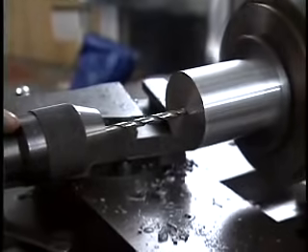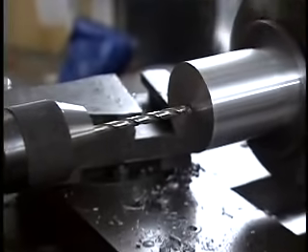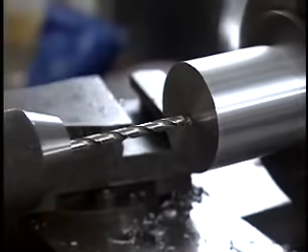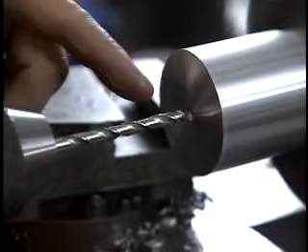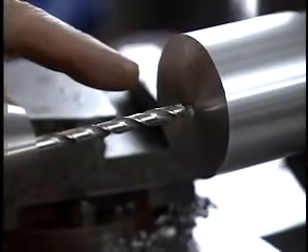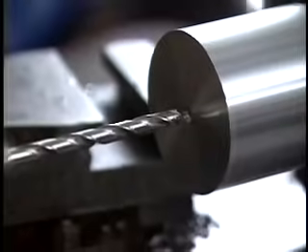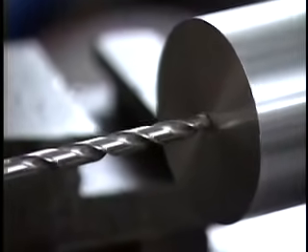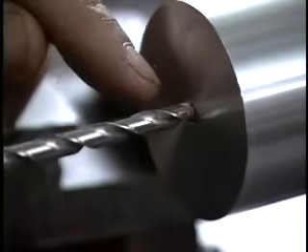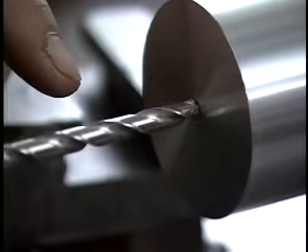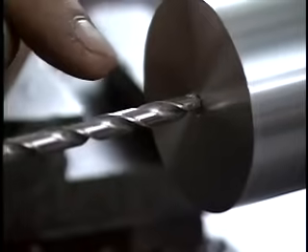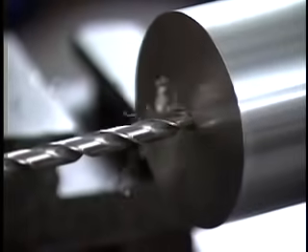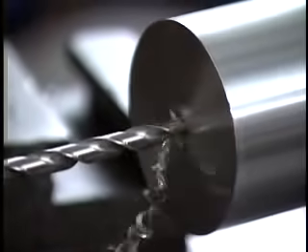It's important to start slowly here. The drill is slightly off-center, and it may be because the tailstock may be slightly out of adjustment. One flute may catch a little bit before the other and pull the drill to the side. You could see the drill jump just a little bit as I brought it in contact. If you start slowly, the funnel will draw the drill accurately into the center of the hole.